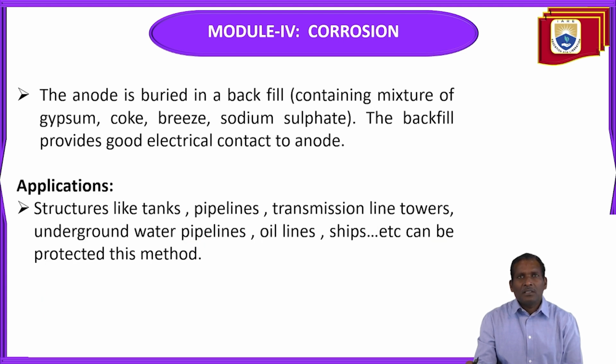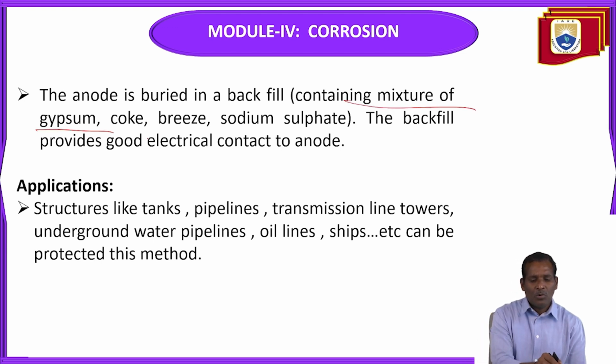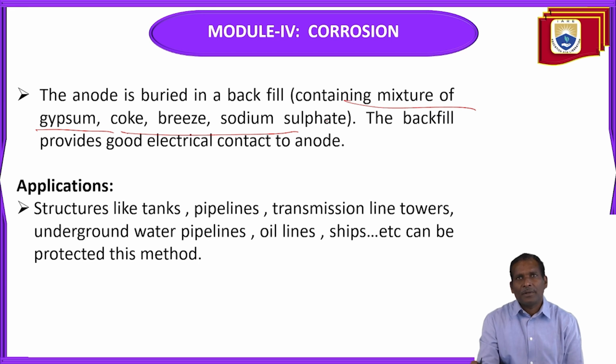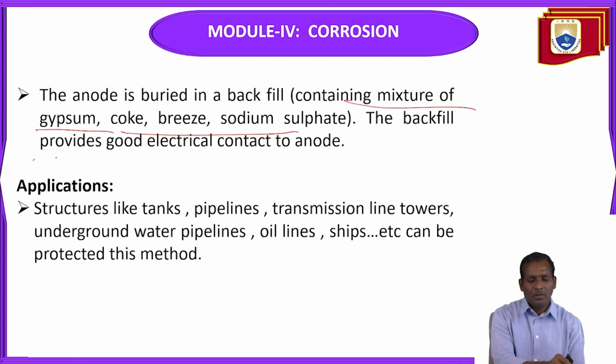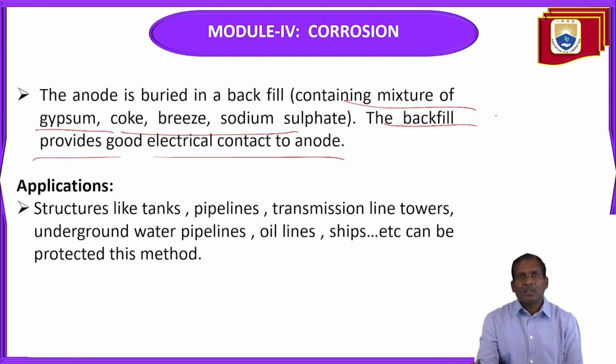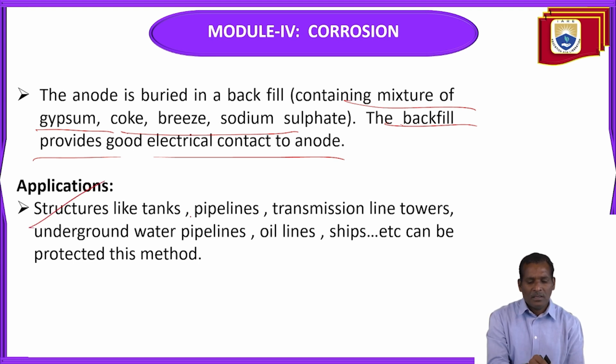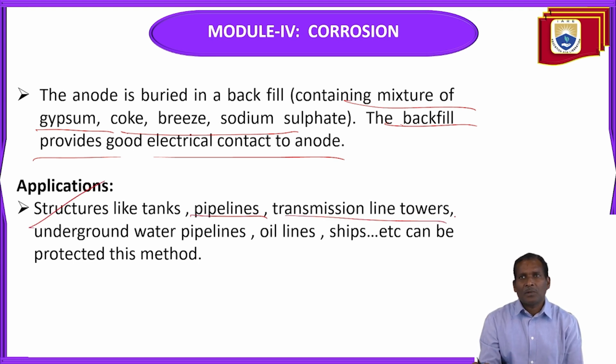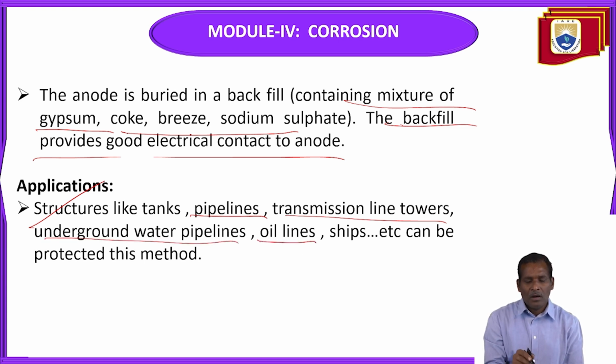So the anode is buried in a backfill containing a mixture of gypsum, coke, grease, and sodium sulfate. The backfill provides good electrical contact to the anode. The applications are structures like tanks, pipelines, transmission line towers, underground water pipelines, oil lines, ships, etc. can be protected by this method.